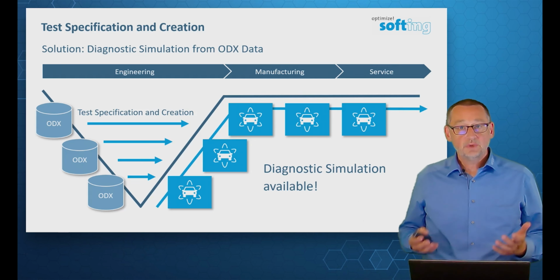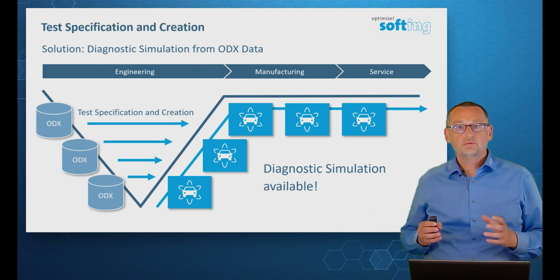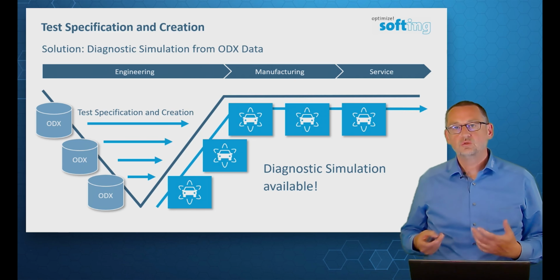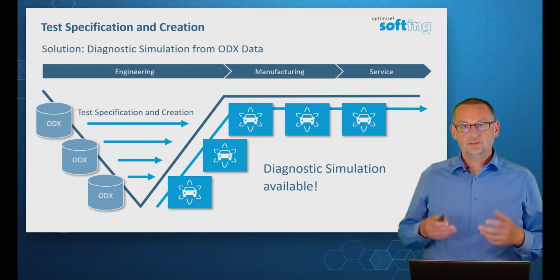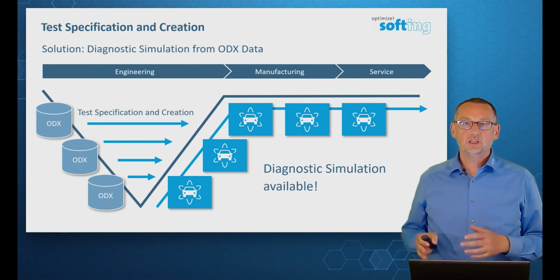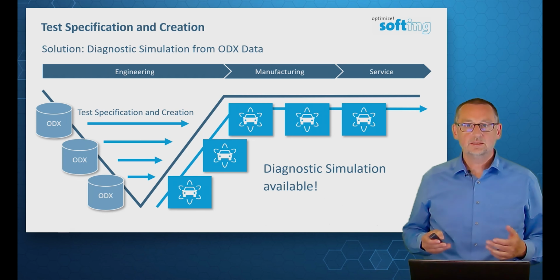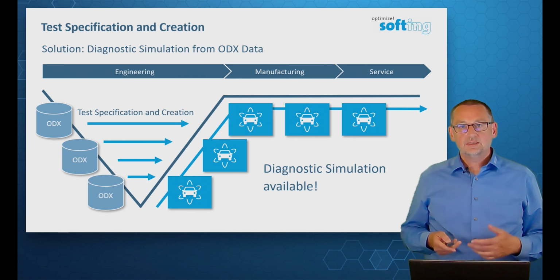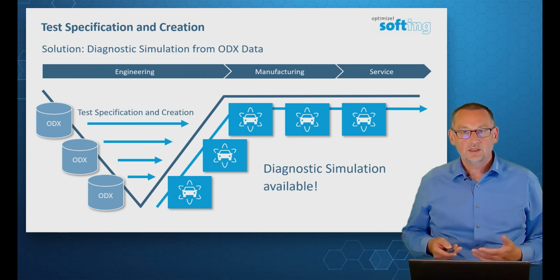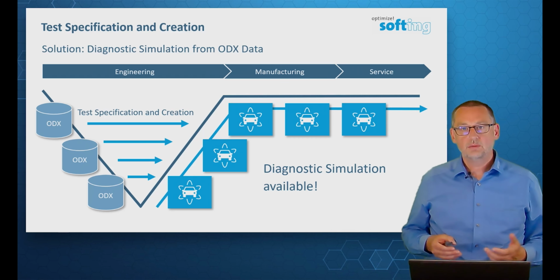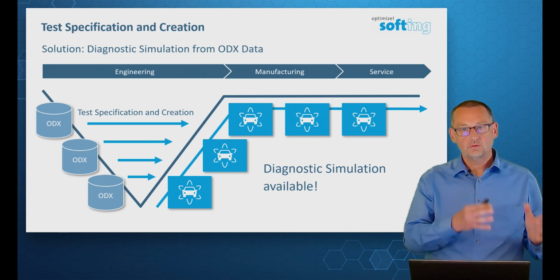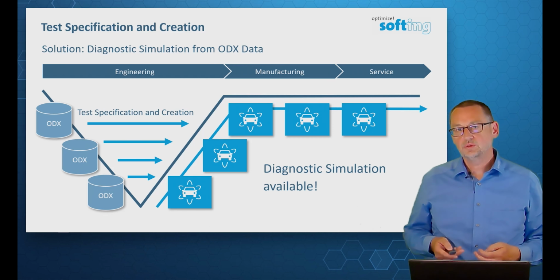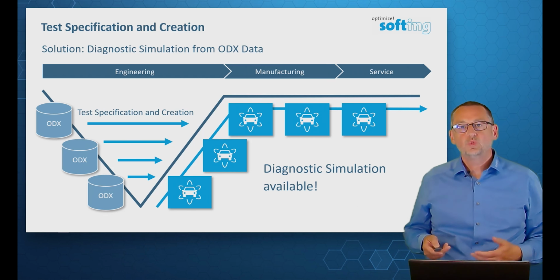The diagnostic specification is the only source for implementing the simulation, which is usually available today as ODX data. In test preparation, creating simulations based on ODX data has proven to be an efficient approach. ODX is the diagnostic specification, which makes it easy to assemble appropriate pairs of requests and responses based on service parameter values. This helps to avoid input errors.